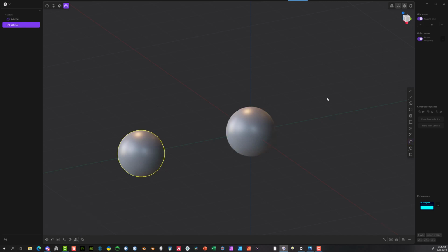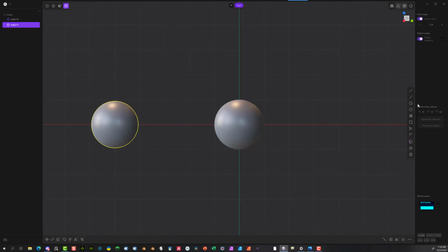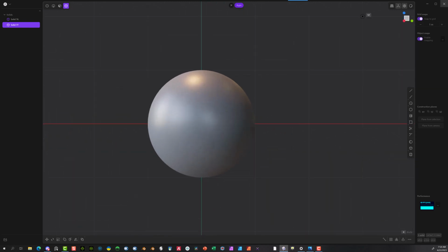Say OK. Now we're going to go back to the x-axis. We're going to create a square section here, a rectangle. We're going to zoom in, take this grid snap off, select the center here, bring this out so it's centered, and I'm going to change this to 2.25. Say OK. So there's that. Now we're going to actually select the sphere. We're going to hit this cutter tool, and I'm going to select this. You can see this outline with the block there, so you know it's cutting.